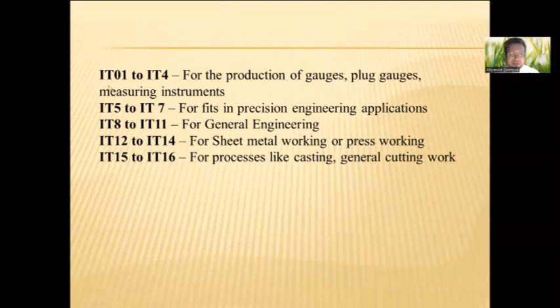IT grade 01 to IT grade 4 for the production of gauges, plug gauges, measuring instruments. From IT grade 5 to IT grade 7 for fits in precision engineering applications.